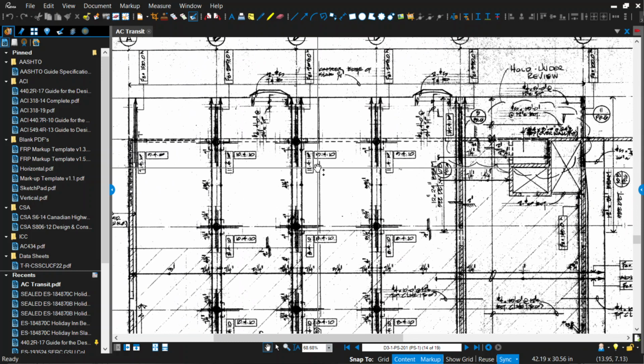If they give information about the length of rebar, does it include development length? Yes. So what do you mean, does it include rebar development length or FRP development length? Rebar, yes. Right, so do we have to recalculate by the development length for FRP? It's not usually the same. We extend it past, yeah. But sometimes we have to apply like 4 layers of CF44. It's really, really long.